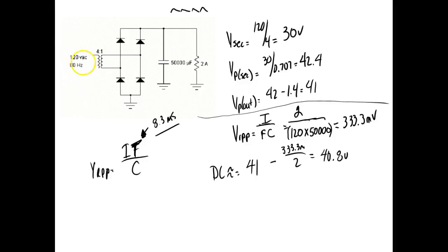But you still have to know that the capacitor is charging according to the pulsing. It's not charging according to that. So a lot of people see that 60 out there and they want to use 60, but full wave, the pulsing frequency is twice the input frequency. Half wave, it is the same, right? Y'all understand that? So that's what you gotta know.